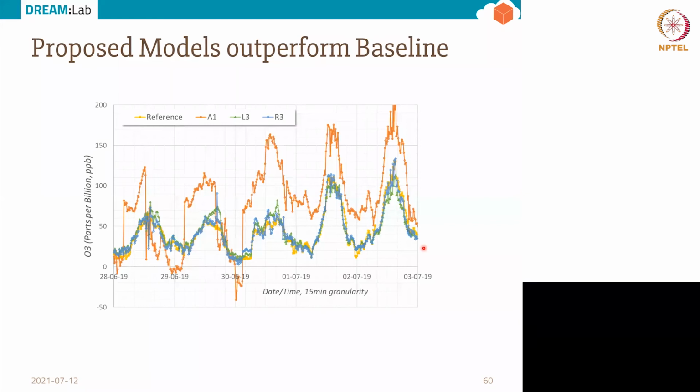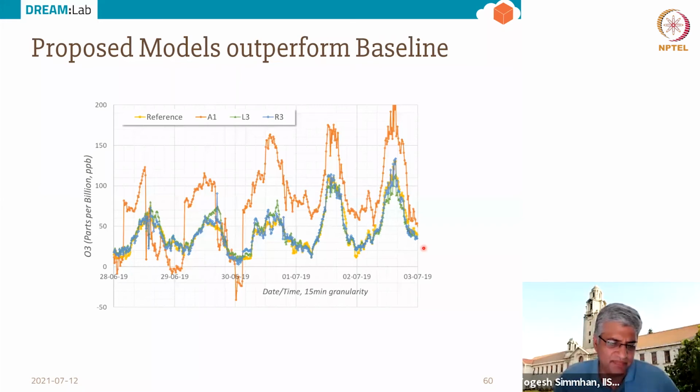We are looking into whether it's sufficient to do it a city at a time, or whether the microclimate within a particular deployment is going to have an impact. Another question is, what is the behavior across time? This validation was done over a 3-month period, but what about a longer-term deployment across a year or 2? How frequently do you need to calibrate? Is the monsoon season going to require a different type of calibration compared to summer? Some of these sensors also degrade over time, so the calibration that you do in year 1 might not necessarily work for year 3.